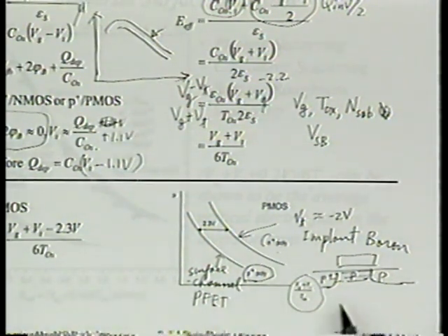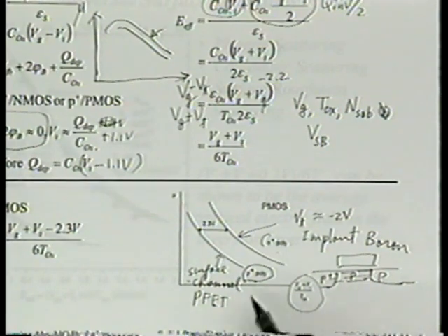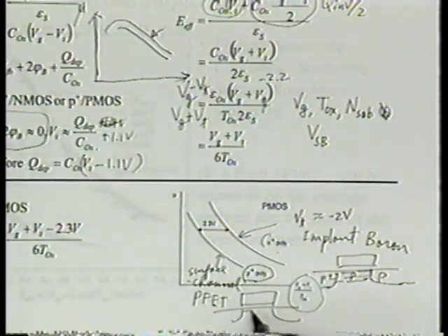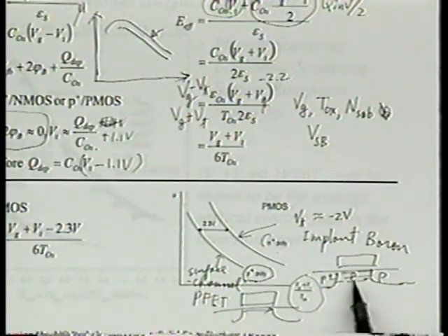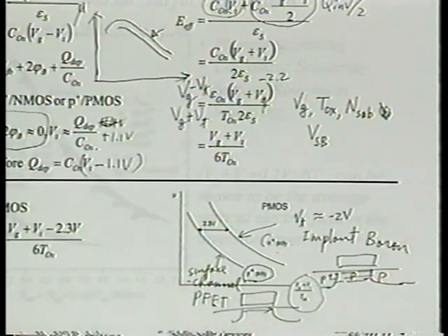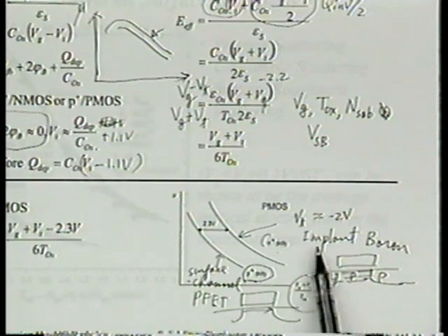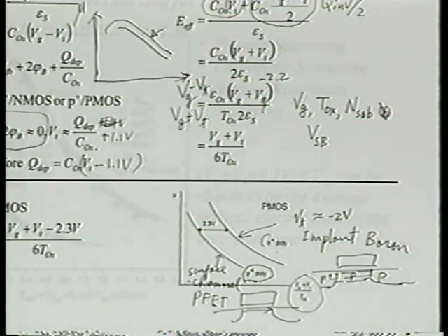Now, why should the mobility of this transistor be higher than the usual design of transistors where current flows at the surface? Doesn't it make sense? It's because here the current is flowing not at the surface, therefore no surface scattering, but because it's flowing in the bulk, therefore it has a bulk mobility. So this data actually fuels the concept that this design is a buried channel transistor.